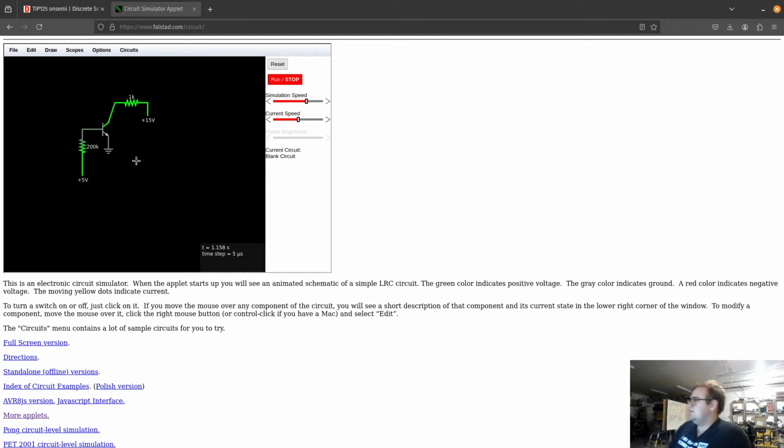I don't know if I'll do that. I might just talk about the circuit like I did before. So, as I said, they just said, oh, there's a current source. It's supplying 20 microamps to the base. I don't have that current source, so I just said, well, I can apply 5 volts to the base through a 200K resistor.